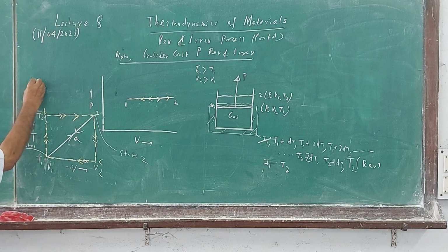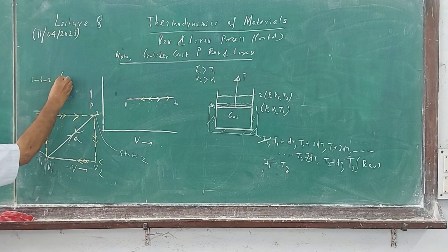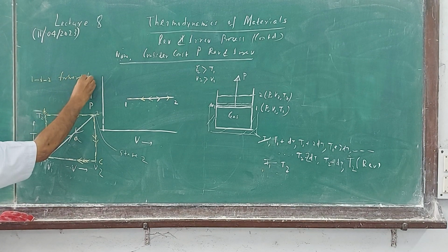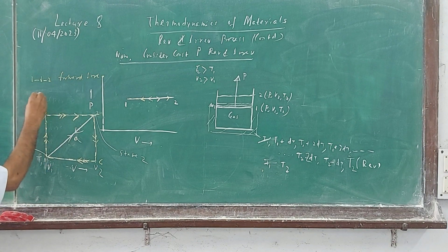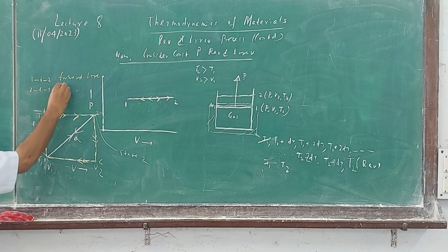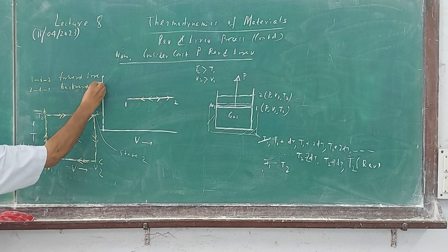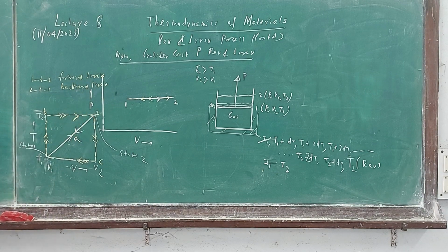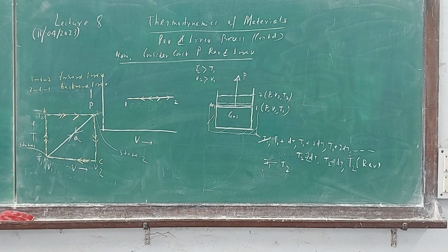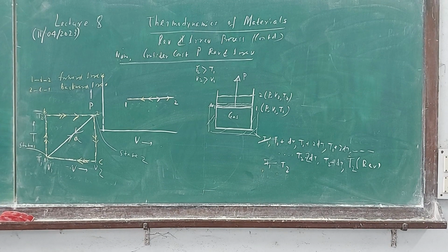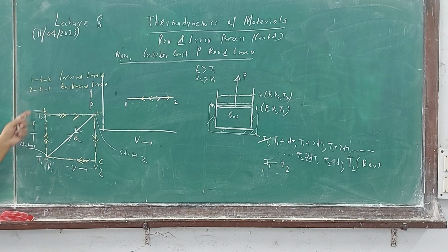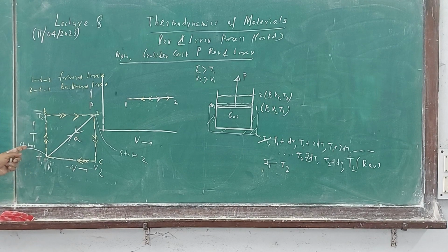You may write this 1B2, forward irreversible, while 2C1 backward irreversible. Constant pressure expansion, or heating, they call it. Backward is cooling, compression. Okay, I will discuss this later on, constant pressure in further detail. But have they retraced?